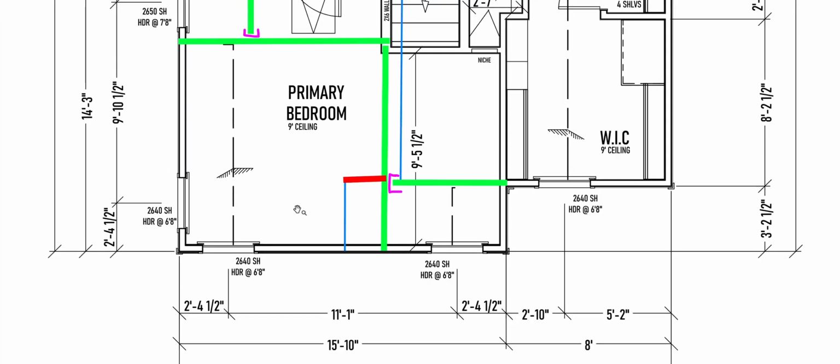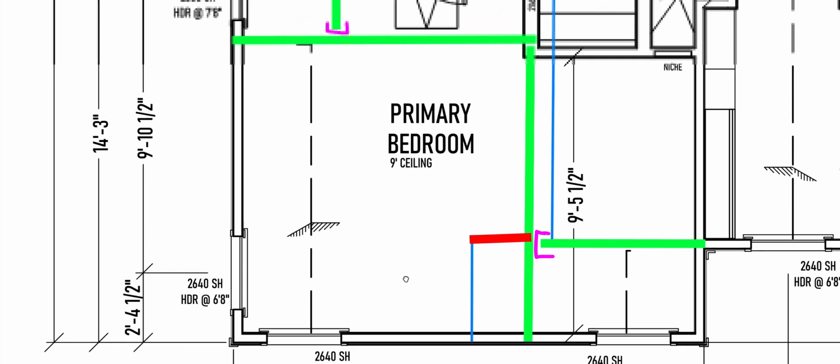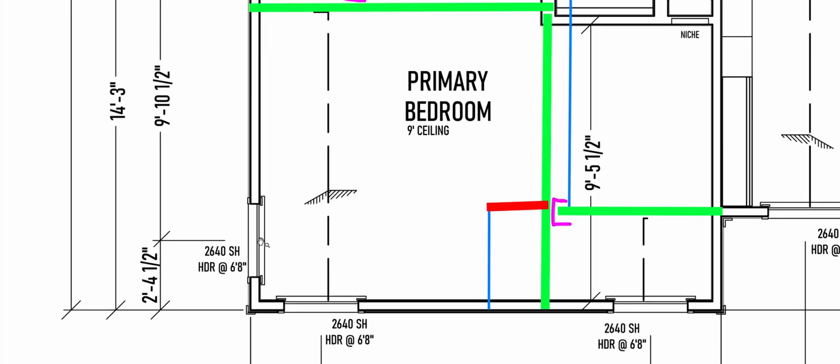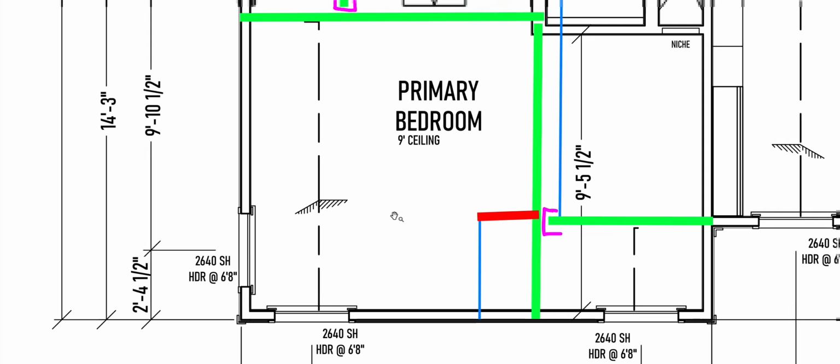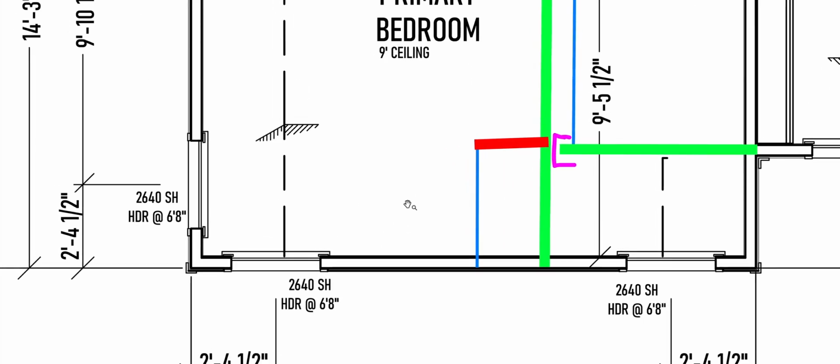So what I know is I could do a few things here. Because this is such a small little piece, I could do something special to avoid needing to put another beam up in here just to hold up like 2 or 3 rafters. That's kind of silly. So what can I do? Well, I can change the spacing of the rafters in this one spot.